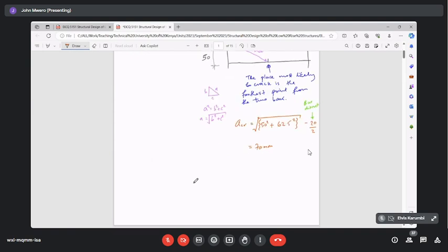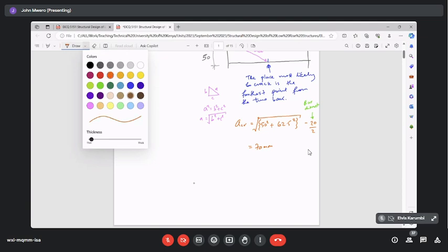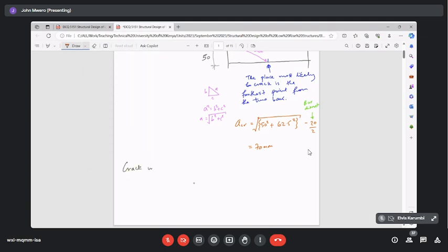Now, at this point, there is an array of equations that have been suggested to give us the crack size. The BS suggests 2 equations. I will not bother with both of them. One is simpler than the other one, and is the one that I will present in this class. If you're interested, you can go and read on the others as well. So the crack width to BS is given by CW is equal to 2.3 multiplied by SCR, which we have calculated, multiplied by the strain in the steel in tension, what we have called epsilon. That's a simpler equation for calculating cracking.